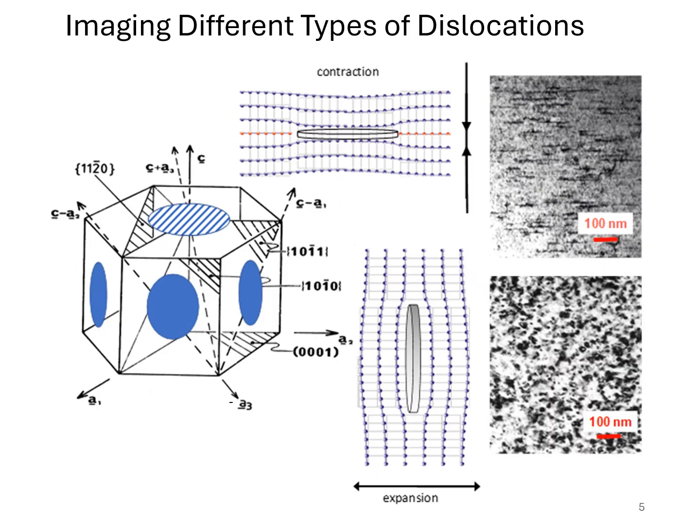And when it comes to radiation damage, there are two forms of what we call dislocation loops, or in cold-worked materials, loops can appear as helices that climb on existing dislocations. But for all intents and purposes, I'm just going to focus on discrete loops in this particular case.